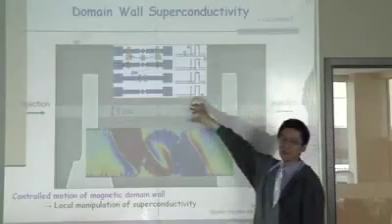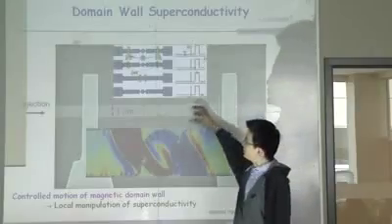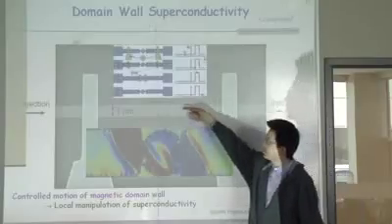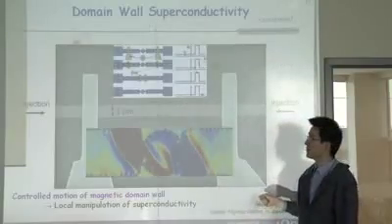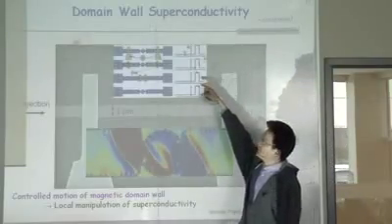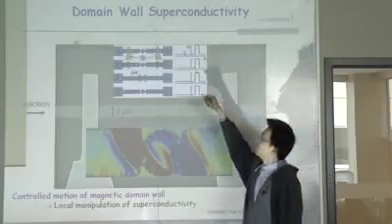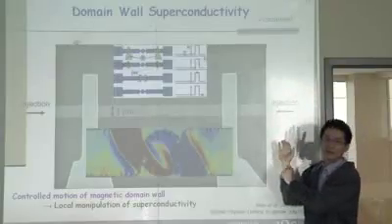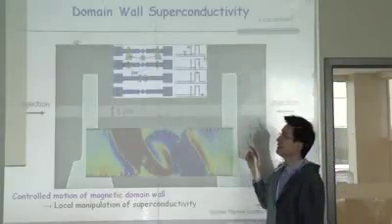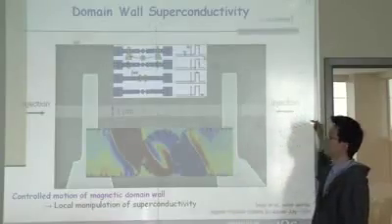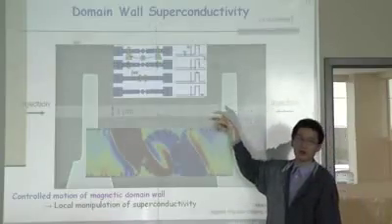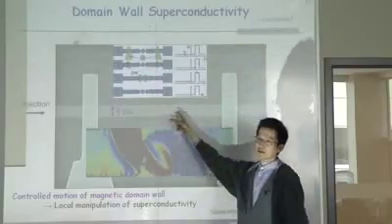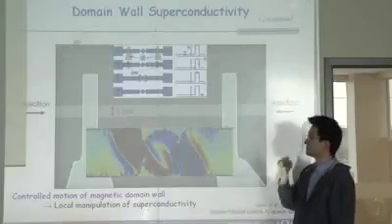What you are looking at is a micron-sized nanowire. We have certain patterned nano constrictions in the middle. The depth of these constrictions is 200 nanometers. So the cartoon on the top illustrates how the system works. We have two very large pads on the two ends. These are the magnetic domain wall reservoirs. They will nucleate magnetic domain walls and inject the domain walls into the wire. When the two domain walls move to the center, they will be strongly trapped at these nano constrictions.